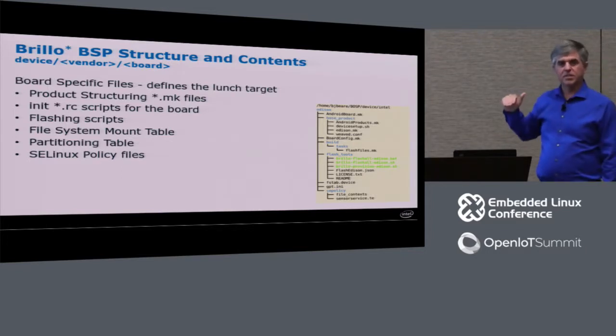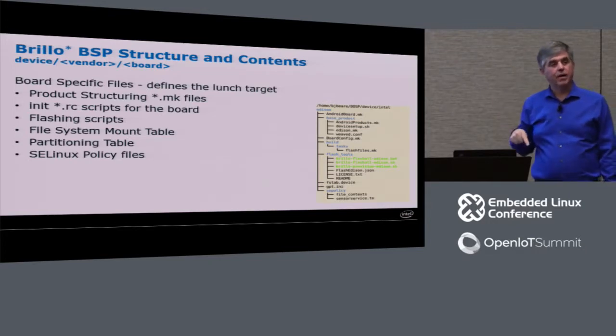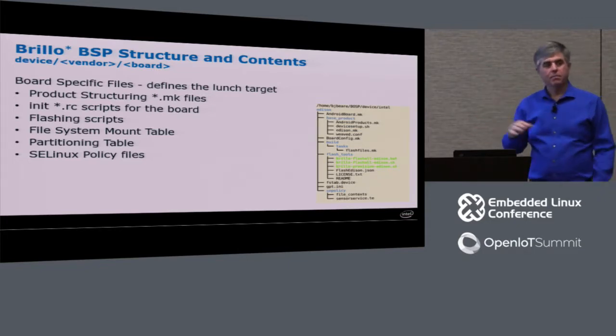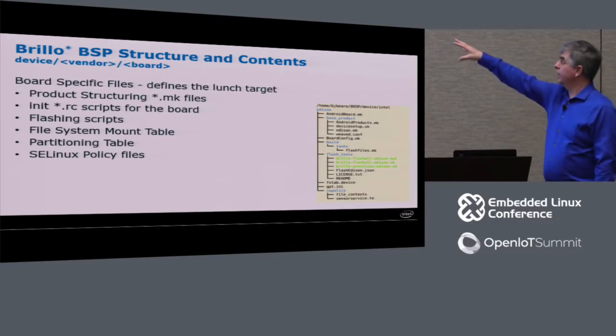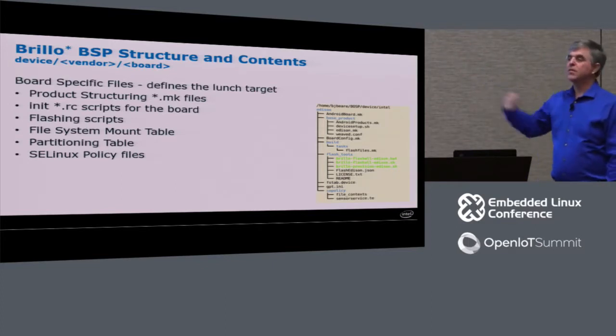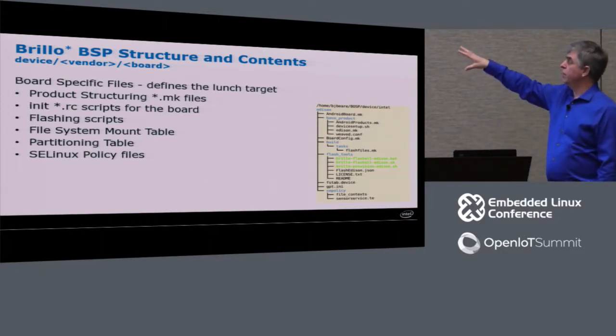The structure of it is similar, but since we have an SoC directory, all the SoC-related stuff for the board has been pulled out of there and put in the SoC directory. And what you'll find in there is a few definitions and a lot of macro calls that just kind of suck in the code that you need. And it makes it really easy to create a new board.